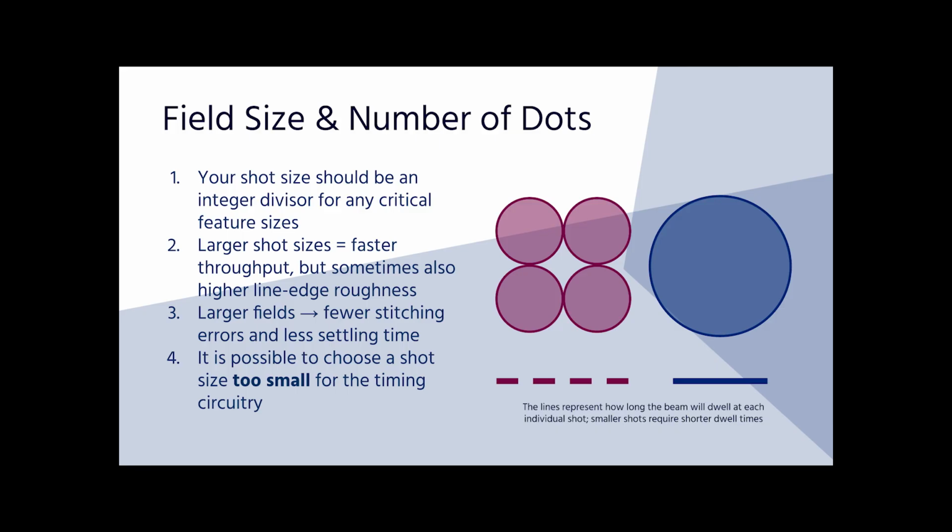The practical minimum dwell time is quite a bit higher than this. I typically recommend dwell times at 0.3 microseconds and above. When members have tried to write faster than this, we've seen some discrepancies due to hardware failing at these high speeds. If running at these high speeds is critical for your work, please reach out for an in-depth conversation. For the purposes of this video, the main takeaway is this.